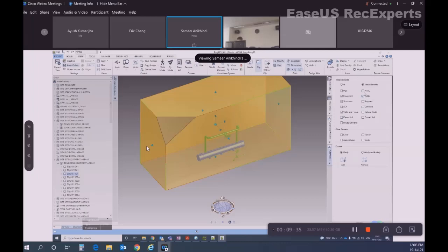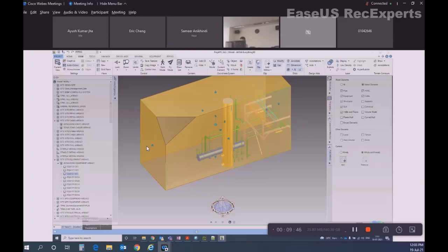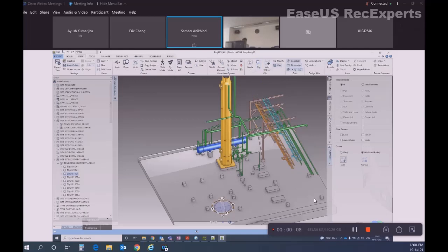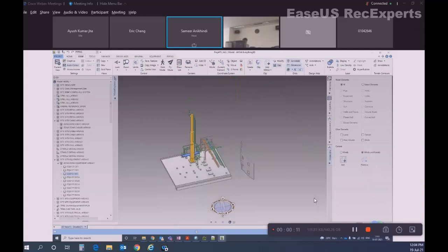Cable, HVAC, and click on add wholly. Or let me use partially. So see, whatever was partially falling inside this volume was added. Similarly, you can remove partially only the cable. I don't want cable elements. Modify box and work on the added clipped model. Once you are done, you can unclip the whole model. Hope the clip is clear.